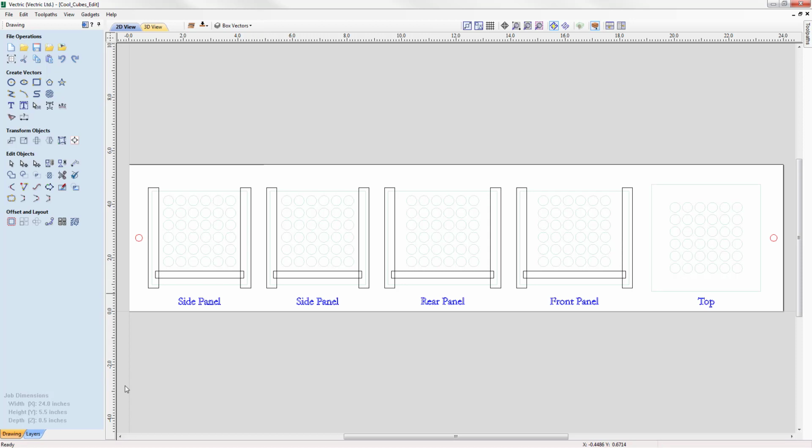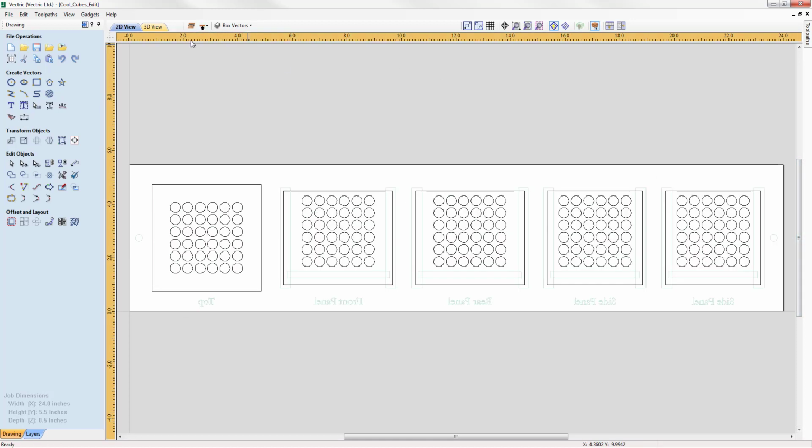We'll then take the material off, and then we'll insert the dowels into the holes in the spoil board, where we'll then look at flipping the material over in this direction, and then position the material onto the dowels to align the X0 and Y0, and then secure the material down in place, and then we're ready to machine the toolpaths for the bottom side, where we'll look at profiling the decorative holes, and then finally look at profiling all of the outlines to cut each of the parts out. So let's go and run the toolpaths.